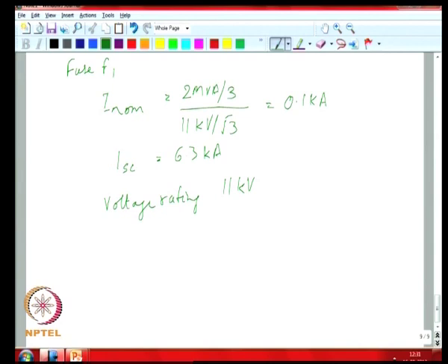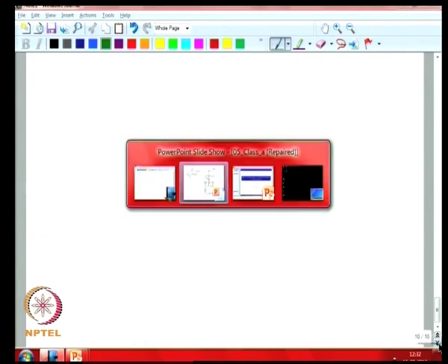If you take it as twice that, you are saying greater than 22 kV. So, this would help you in selecting the fuse. Okay. So, you look at the fuse in terms of the nominal current it needs to carry, and also your peak current that it would need to interrupt if there is a fault on the distribution transformer on the primary side. Okay.